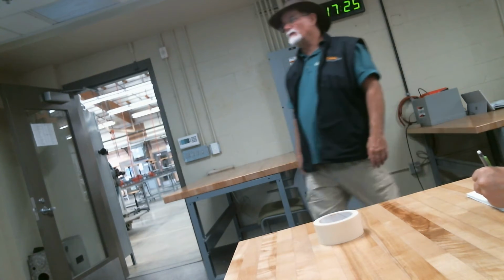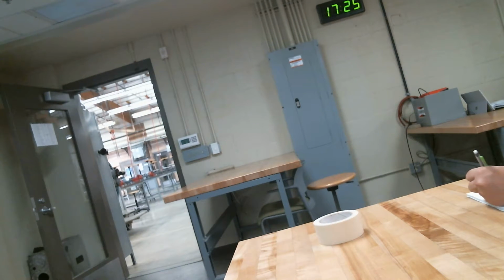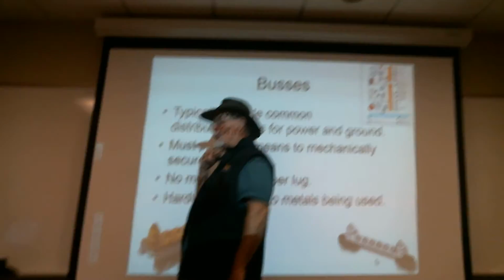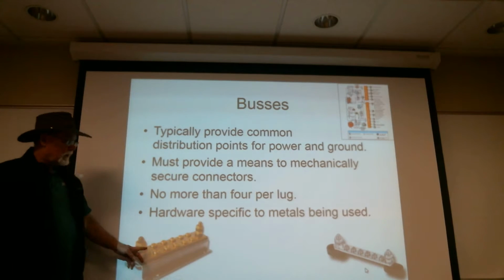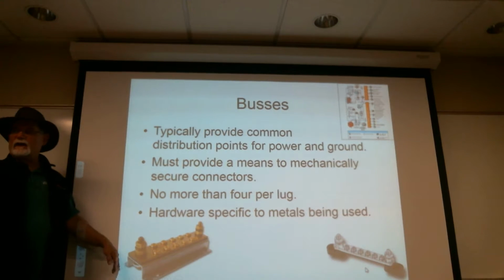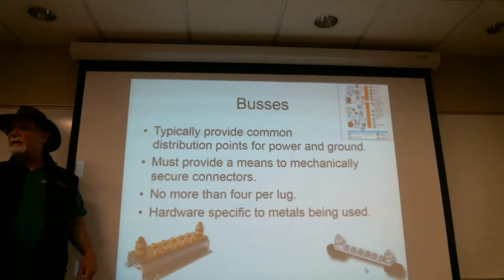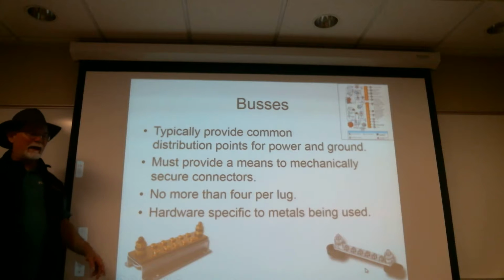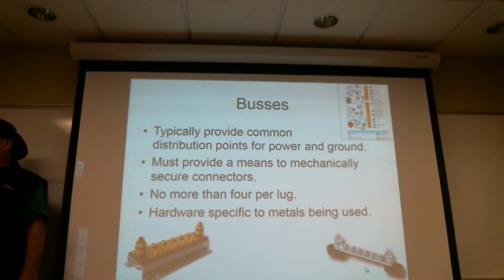So it's good for power distribution, ground distribution, and gives you a very good mechanical means to connect stuff together. So rather than a freestanding crimp, you've got solid eyelets coming together at the same point. It's very possible to have a bus that's really more of a connector plate. Each set of paired screw holes is independent of each other. And where you want to gang them together, they have a little device that hops over the fence and gangs them all together.